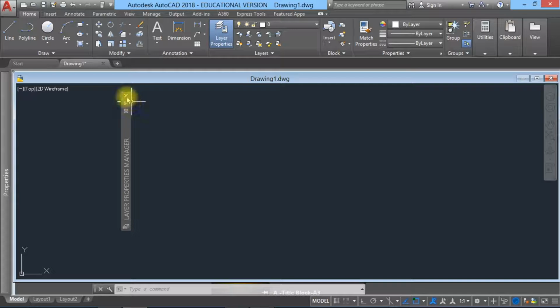Let me close this one. As I told before, your line weight, which is going to define graphically the texture or definition of your design, is going to be according to your layer color, and you have to adjust those line weights according to the colors already described on page 6 of the same document, I mean the task 1 floor plan procedure document PDF, which you have.